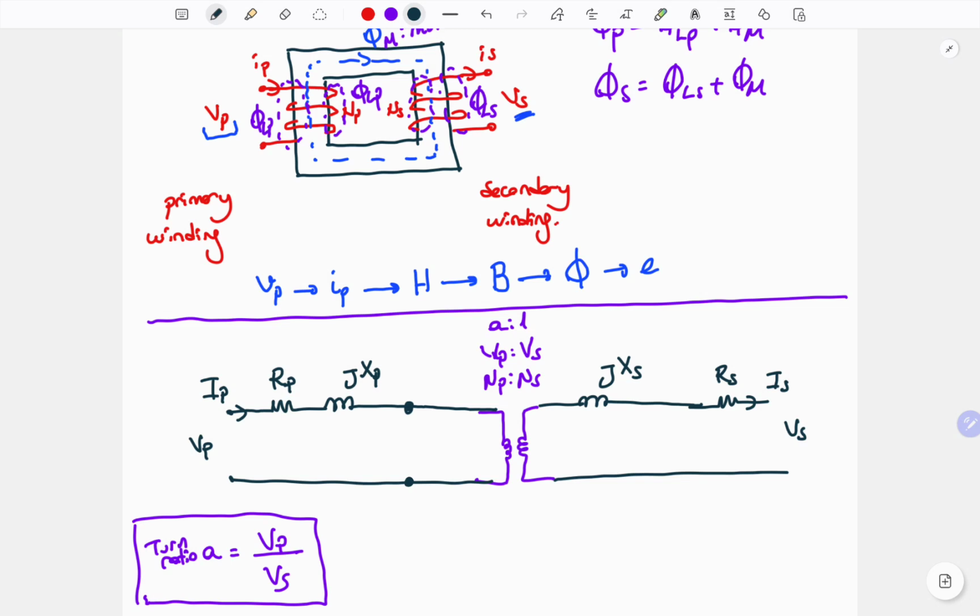The reason is that initially the system doesn't have to supply the load, but to be able to operate the transformer, we have to satisfy the core related power requirements from the input side. So because of this, it is represented at the primary side.